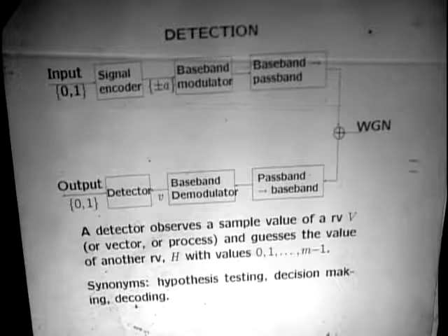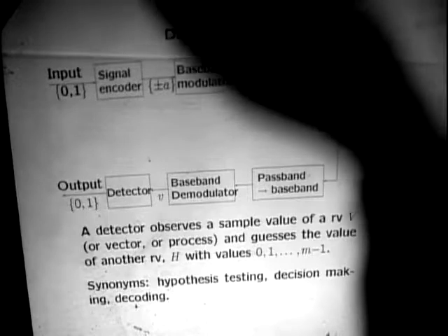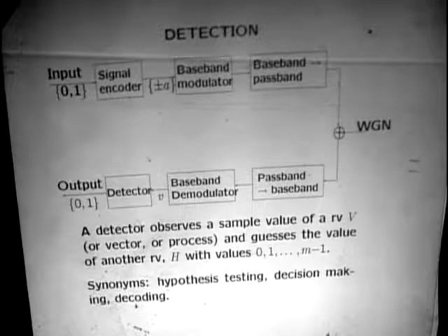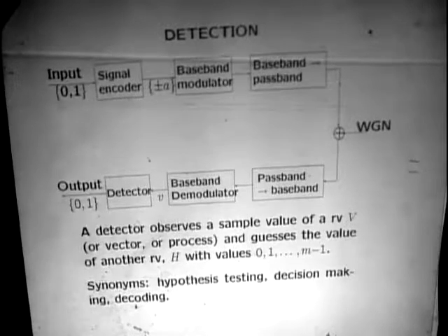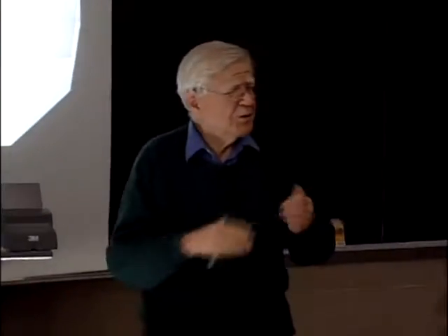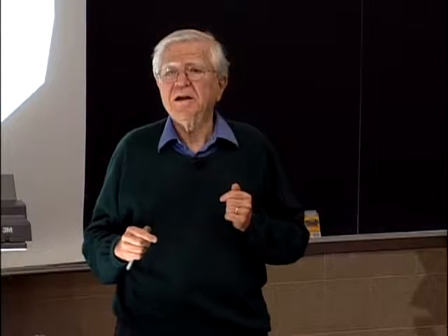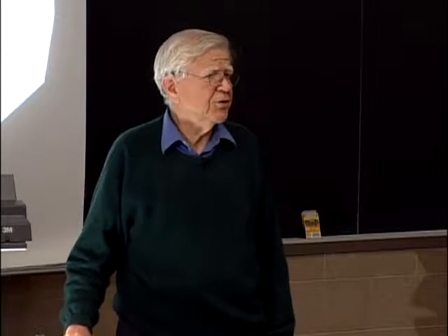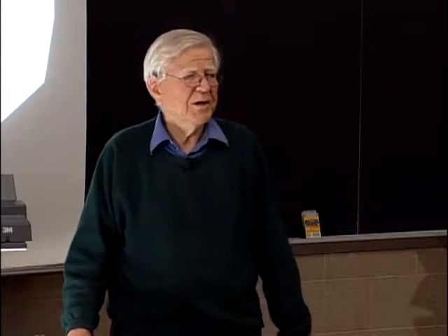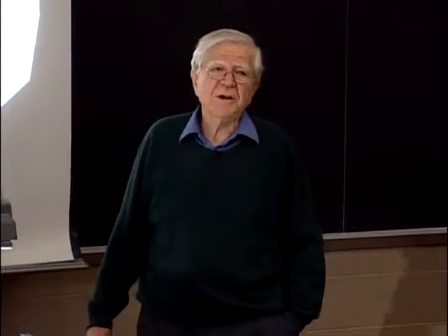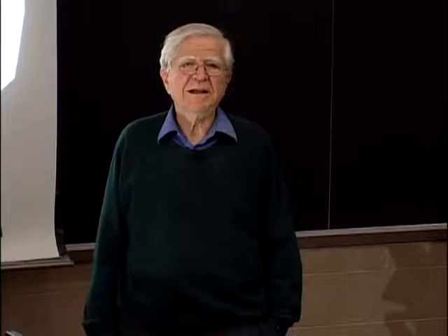You sort of have some kind of clue that if you send the whole sequence of bits in a system like this, and you don't have intersymbol interference, and the noise is white, so it's sort of independent from time to time, you're going to get the same answer whether you send a sequence of data or whether you just send a single bit. And we're going to show later that that, in fact, is true. But for the time being, we want to understand what's going on. And to understand what's going on, we take this simplest possible case where there's only one bit that's being transmitted.